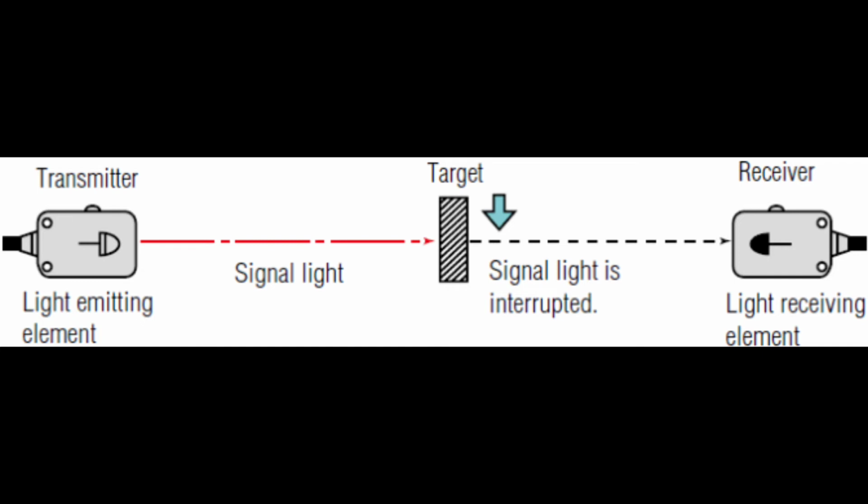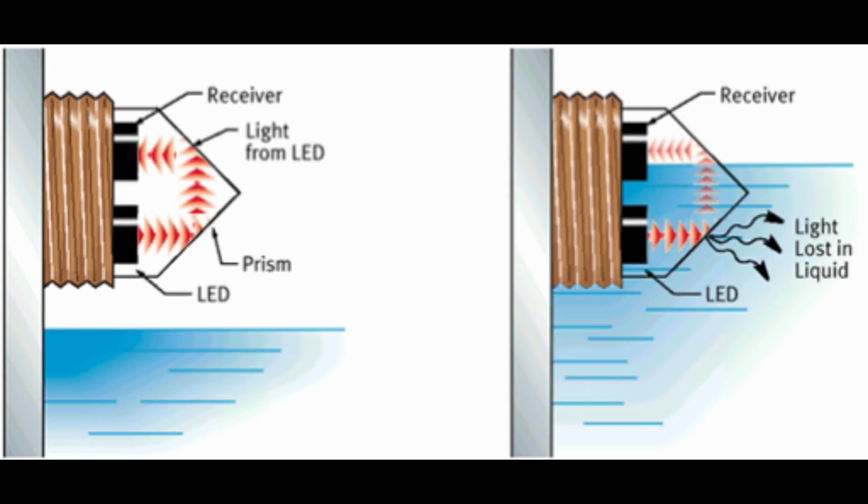An optical proximity sensor is also called a light beam sensor. These contain a sensor and a light source. The sensor is used to detect the light whenever the light source produces light. These sensors emit a light beam that is capable of detecting all sorts of objects. It has three models: reflective, through beam and retroreflective.